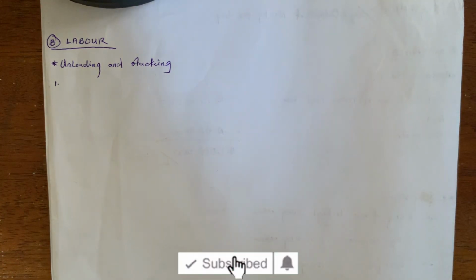I know when you hear ton, you might be thinking that it is a very plenty amount of reinforcement, but 1 ton of 12 reinforcement is just about 94 lengths of reinforcement. So you see that it is not what you think it is, although it might be heavy, but they are capable. So 1 ton of 12 reinforcement bar is a quantity of 94 lengths of reinforcement.